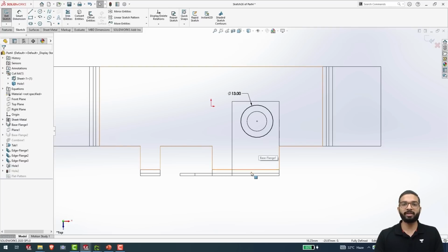You need not specify the dimensions every time you create your 3D models. If you have created some feature previously, you can use its reference to create further features. This was a small example of how you can create these references. And now that I have set it concentric with this circle, you can see that without giving any other dimensions, my sketch is now fully defined.